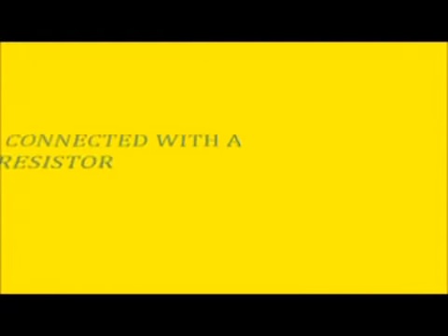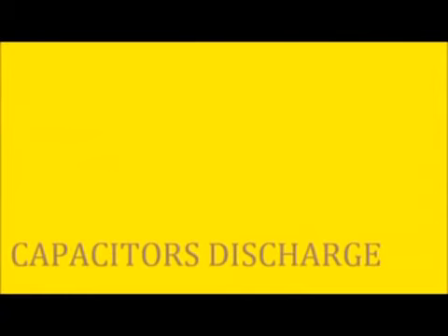Once the capacitor is discharged, keep its leads connected with a resistor or a piece of wire to keep it discharged. Capacitors are most likely to be discharged after a few days, so long as there is no internal battery.